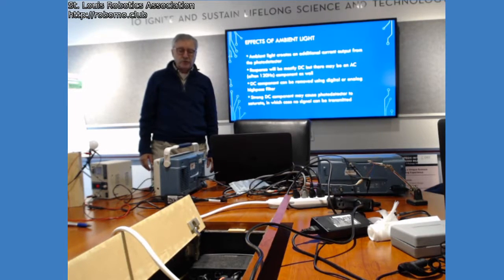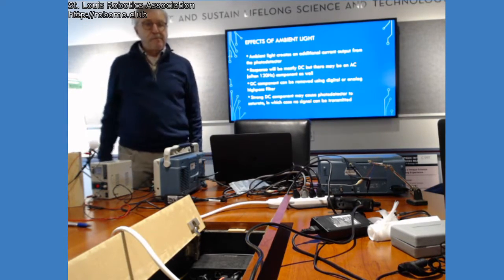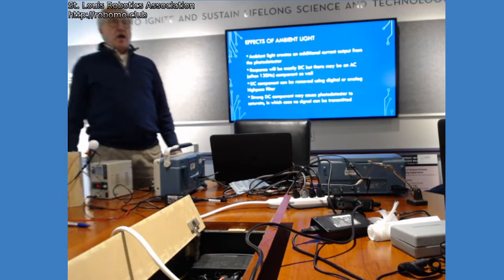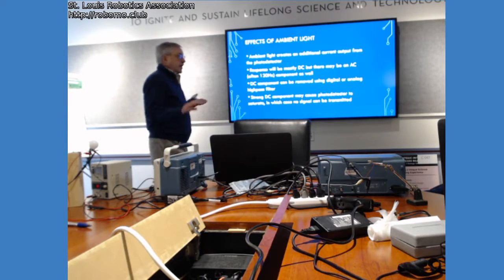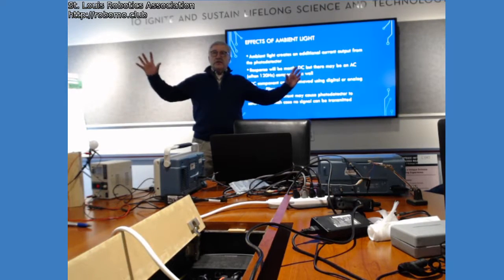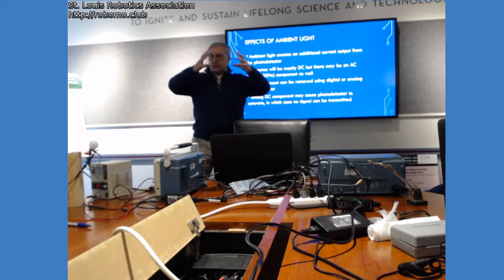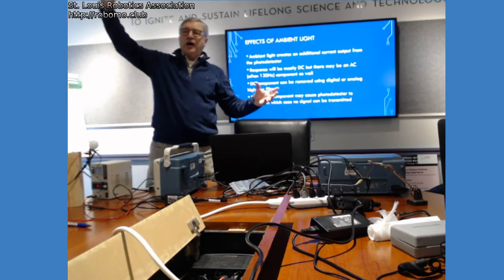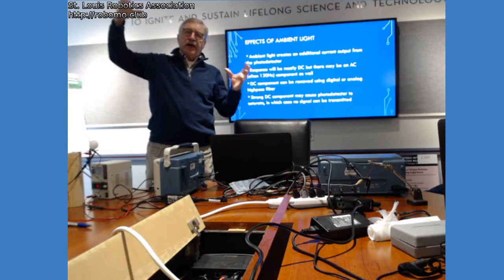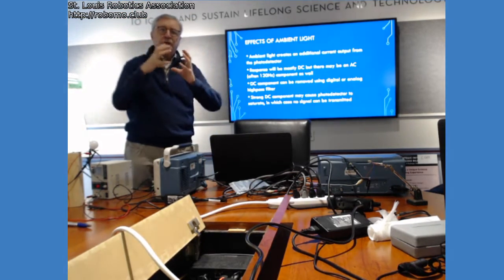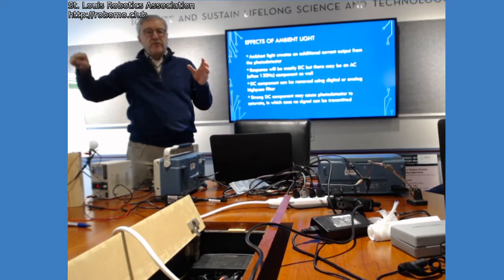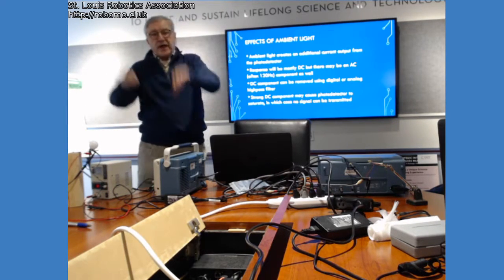Hey Dan, on the LEDs, are they turning them off altogether, or is it a voltage fluctuation at that frequency? I think in most cases what they do is they actually take either just the voltage offline, in other words, just the 120 volts AC, or they go through a transformer and bring that down. But at any rate, they have what winds up looking like a full rectified sine wave, and so they're actually going all the way down.